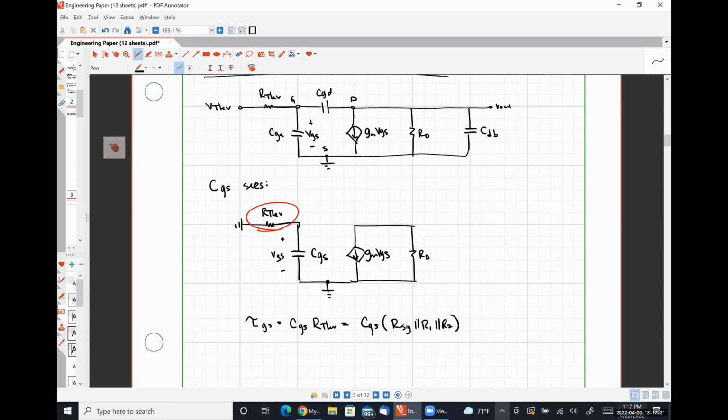Any questions, comments, concerns about the analysis that we did here? All of this bit right here shorts itself out. It does not contribute to the resistance in any way, shape, or form, right? So effectively, if we tied, just to be clear here, those two ground nodes together and look in through the capacitor's open circuited terminals, all we would see is the Thevenin equivalent resistance. All right.